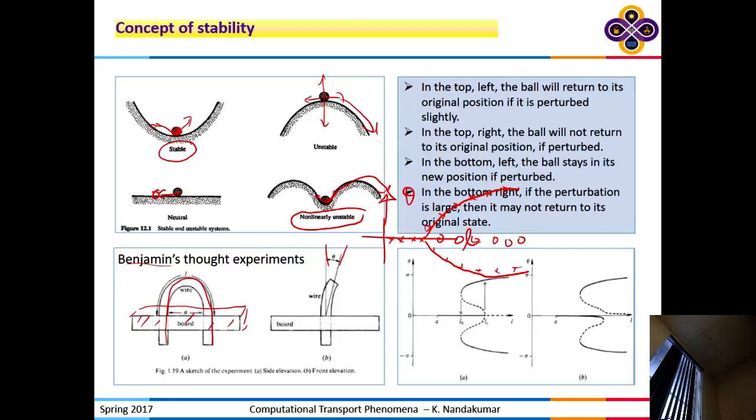Okay? And you can determine the stability of this, and you can also have variations on the theme, which is in some cases you have a stable solution and the solution folds back on itself. Then there is another stable solution there. So if you continuously increase the length, it will snap and go to that. But when you decrease the length, it doesn't snap back at the same position, it snaps back at a different position.